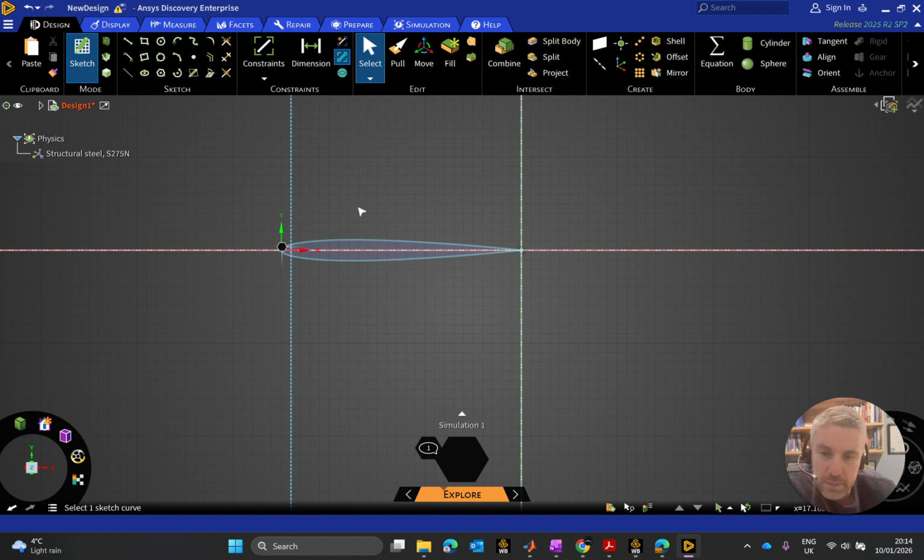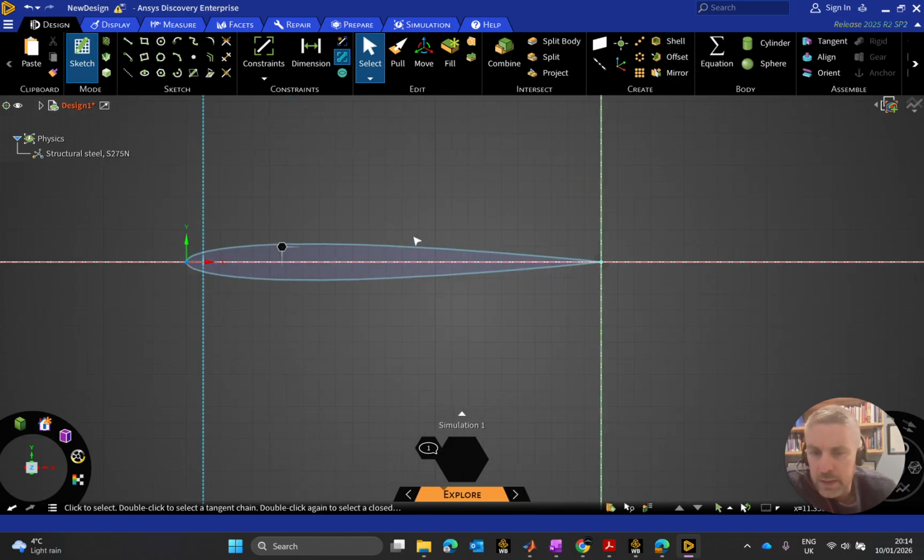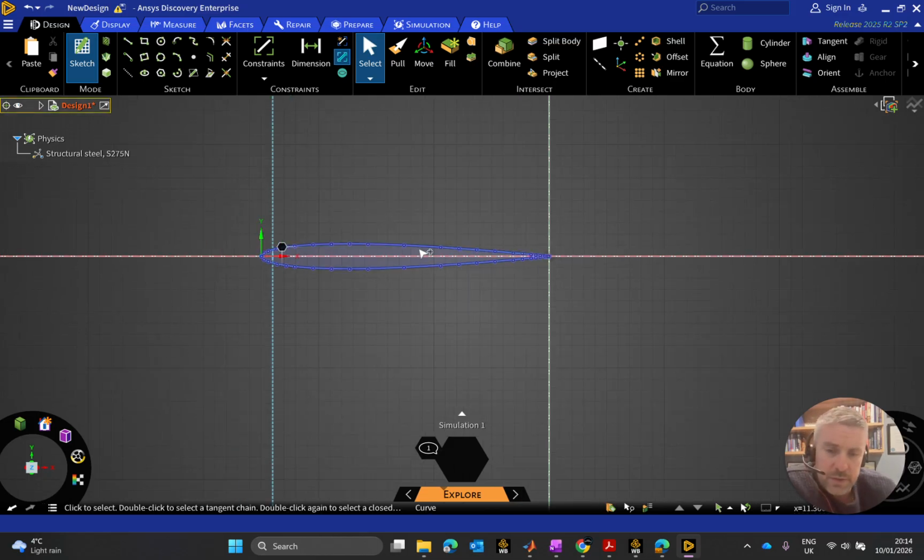What generally happens is that the air goes immediately over. What keeps the air pinned onto the airfoil to follow the shape of the curve? As the air comes over, why is it encouraged round here? Some people tell you that it's because of the no slip condition on the airfoil, but that's not strictly true. The no slip condition does keep air on the surface here, but that isn't what contributes to accelerating the air, the change in the direction of the air.